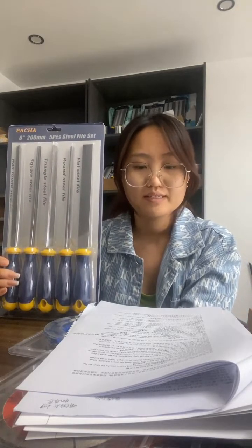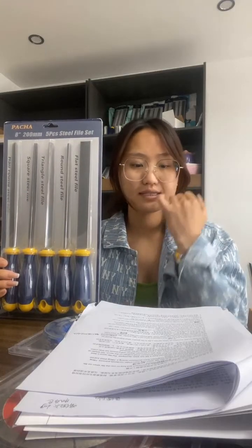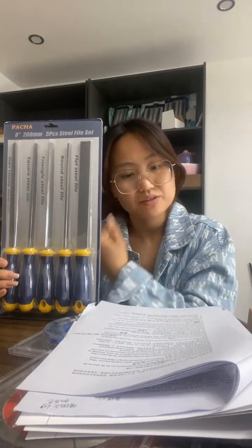This breaks up the filings with an open throat and allows the file to clear. This also overcomes chatter and prevents too large a bite. By using a shearing stroke toward the left, a good finish can be obtained.